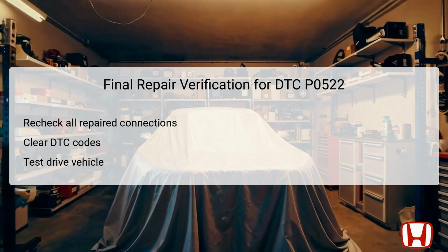Continuous monitoring of the rocker arm oil pressure values during the test drive is also essential to confirm that the readings are now within the expected thresholds. If, after the road test, the error code does not reappear, it signifies that the repairs were successful. Document the completed steps for future reference, ensuring that the same issue does not recur due to similar circumstances.